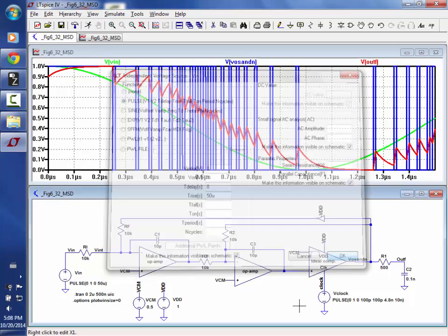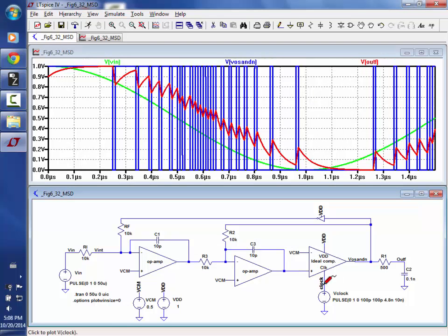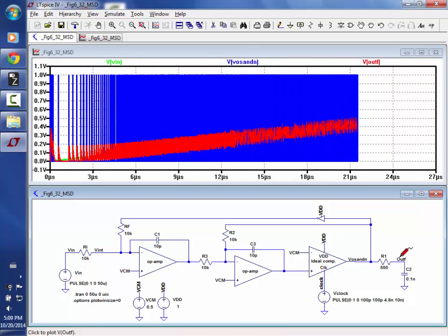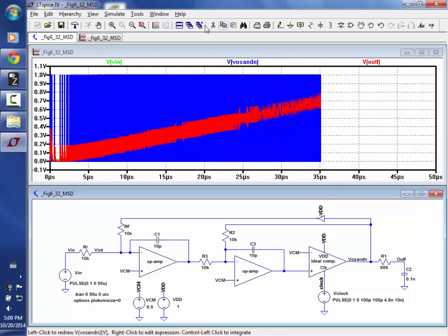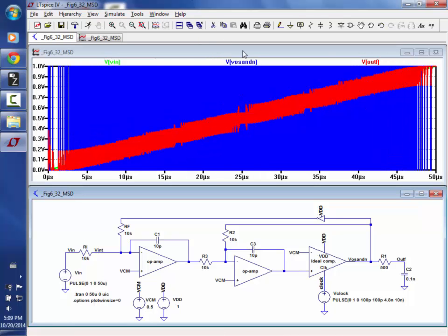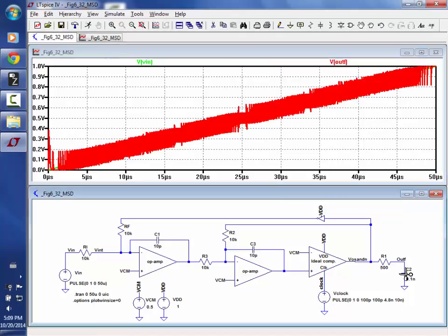So that's a ramp. Then we'll sim for 50 microseconds. We'll start saving data at 0. Okay, I think that's all we need. So we hit run, and let's see what our filtering does. Let's get rid of this dude, and let's put a little more filtering there.